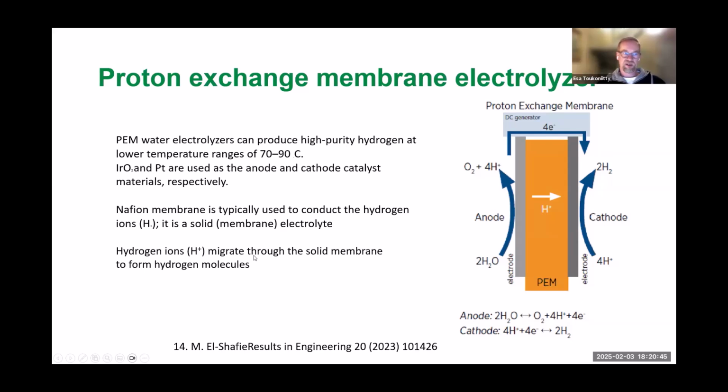The membrane here is very thin, a kind of polymer film, and Nafion is the trade name for it. I think in some materials there is more discussion about the material and how it works, but it's crucial. The main thing here is that the electrodes are separated with this membrane that allows only movement of protons from side to side.